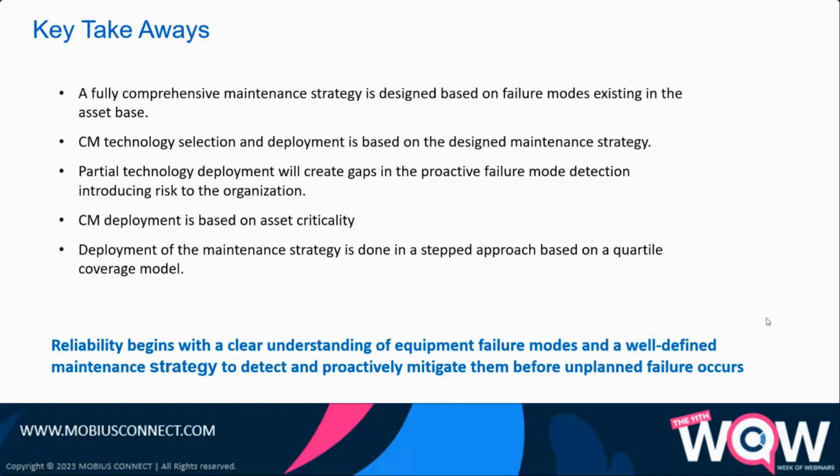So the key point here is that reliability begins with a clear understanding of the equipment failure modes, and then a well-defined maintenance strategy associated with those failure modes to detect and proactively mitigate them before unplanned failure occurs. Next slide, please.